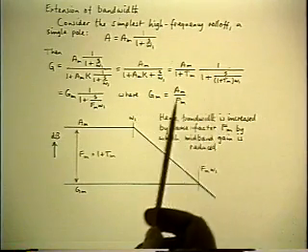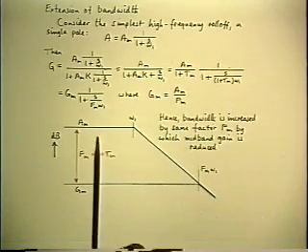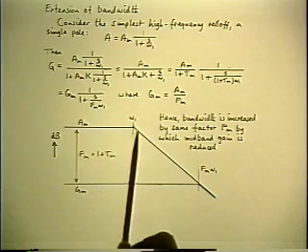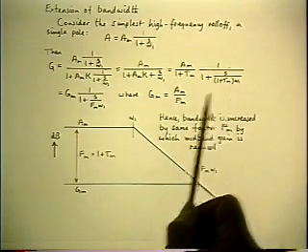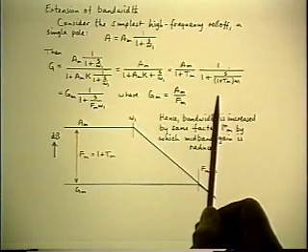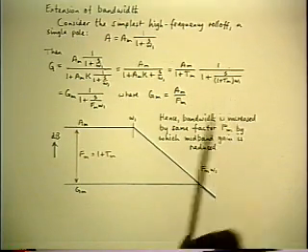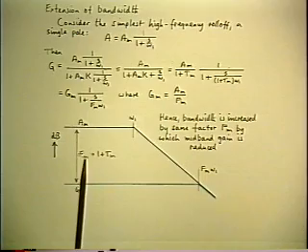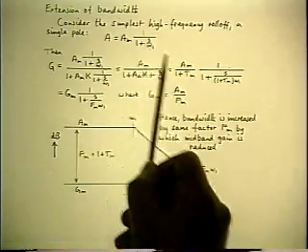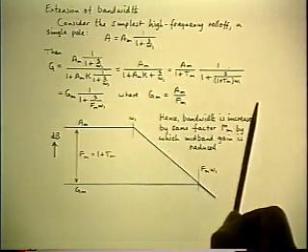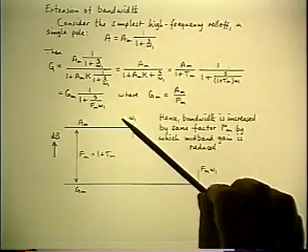Because the algebra shows that the relationship between the two flat gains and the two corner frequencies satisfies the gain bandwidth trade-off. It's the same ratio. Because the ratio of the midband gains is FM, so is the ratio of the two poles. Therefore, the two poles lie on the same asymptote.